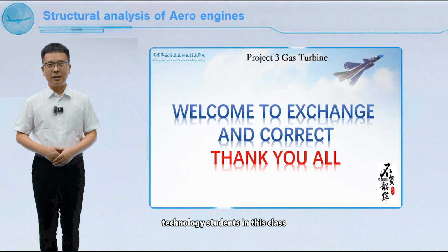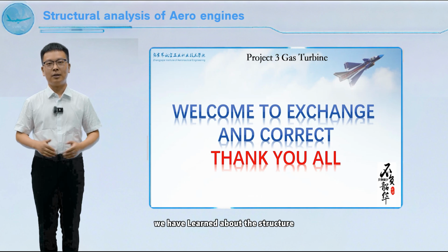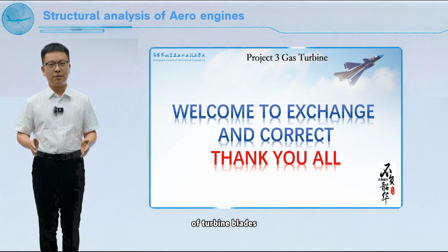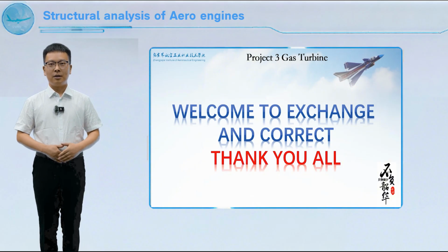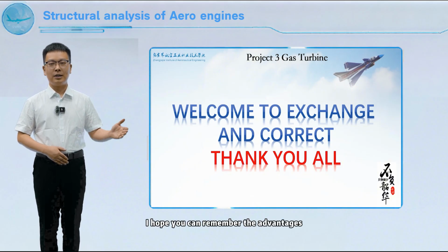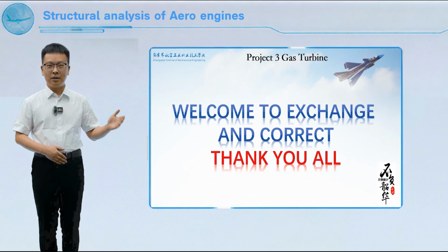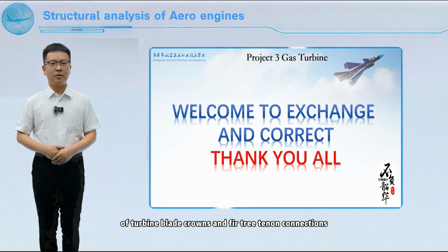Students, in this class, we have learned about the structure and characteristics of turbine blades and the connection between turbine blades and wheels. I hope you can remember the advantages and disadvantages of turbine blade crowns and fir tree tenon connections. Thank you.